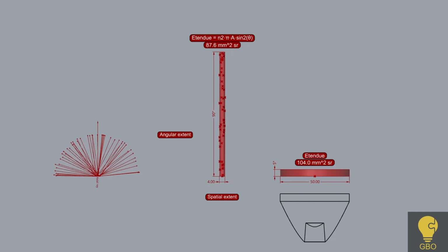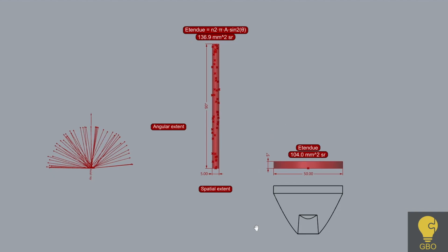Assuming a realistic lens efficiency of around 85-90%, the source output can now realistically fit in the distribution. So, a 50 mm lens producing a 5 degrees beam can handle a source no larger than about 5 mm in diameter, nowhere close to the 14 mm LED that we started with.